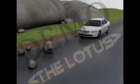Anti-lock braking system. Let's take a closer look at how they work. When the driver fully applies the brakes in a vehicle without the anti-lock brake system, the brakes can lock. This causes the wheels to stop turning, which makes the tires skid. Skidding tires have very little grip and are not effective at stopping or turning the vehicle, so the driver may be unable to take evasive action.